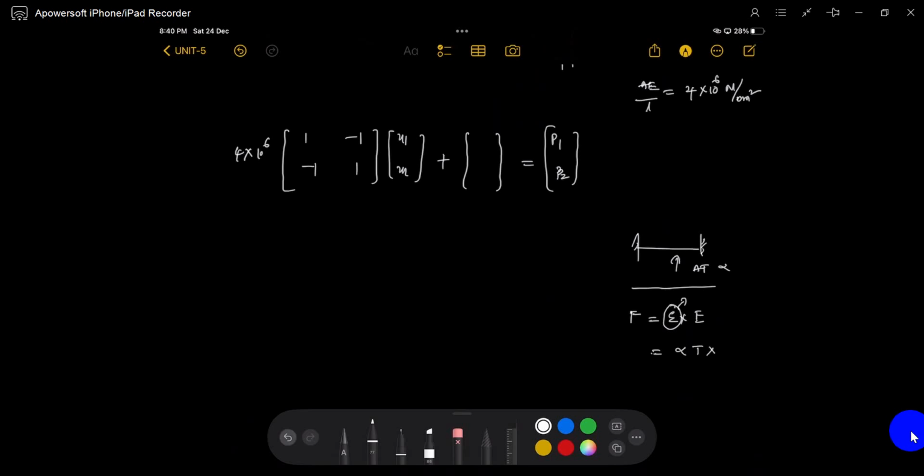So alpha delta T L is the displacement experienced when we allow the thermal displacement, but if we restrain the displacement, it will convert into a force. How much displacement do we restrain? The restrained displacement divided by length gives the strain, times Young's modulus. Understood? So L and L you can cancel it. Young's modulus, temperature rise and thermal coefficient give the force.